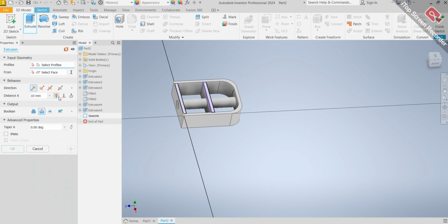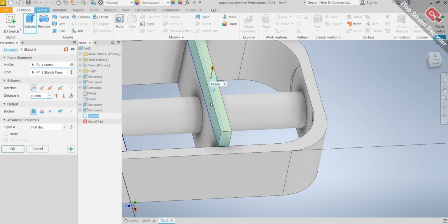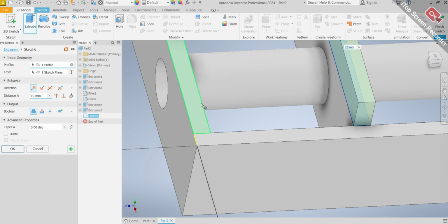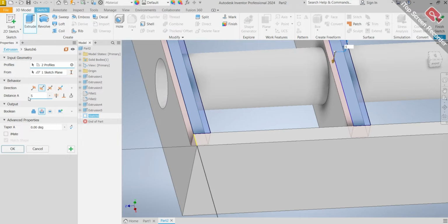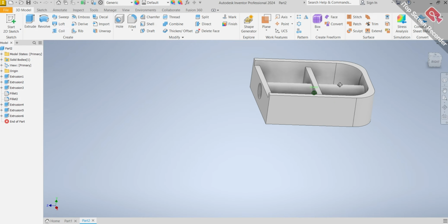Watch please, and I click on cut now. No cut to. No, we're not doing cut to. Not all through. So just in this. First, you click here, not extrude. You click here. We're not extruding. We're not making it a solid. We're cutting. So what are we cutting? What's the thickness? Just 5. Put 5. You click OK. So we have something like this now.